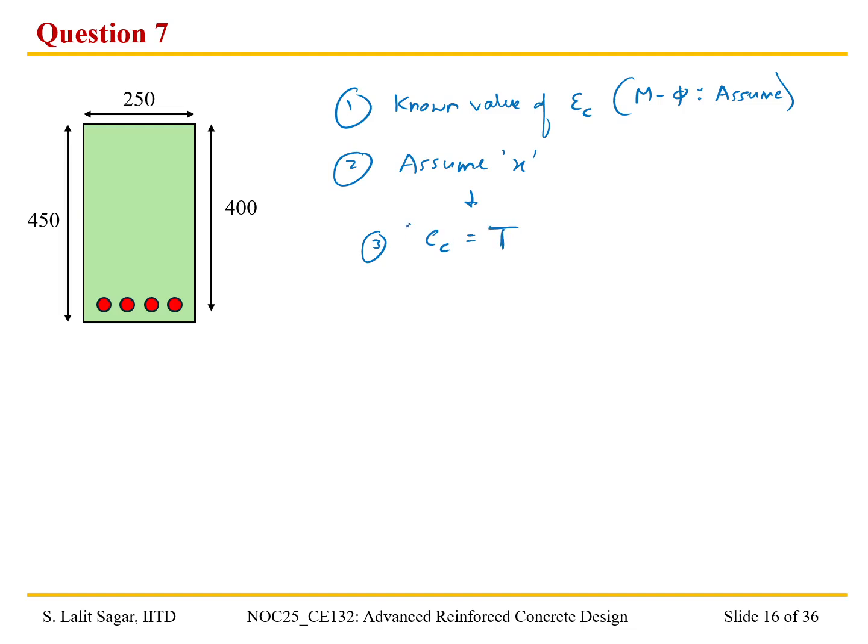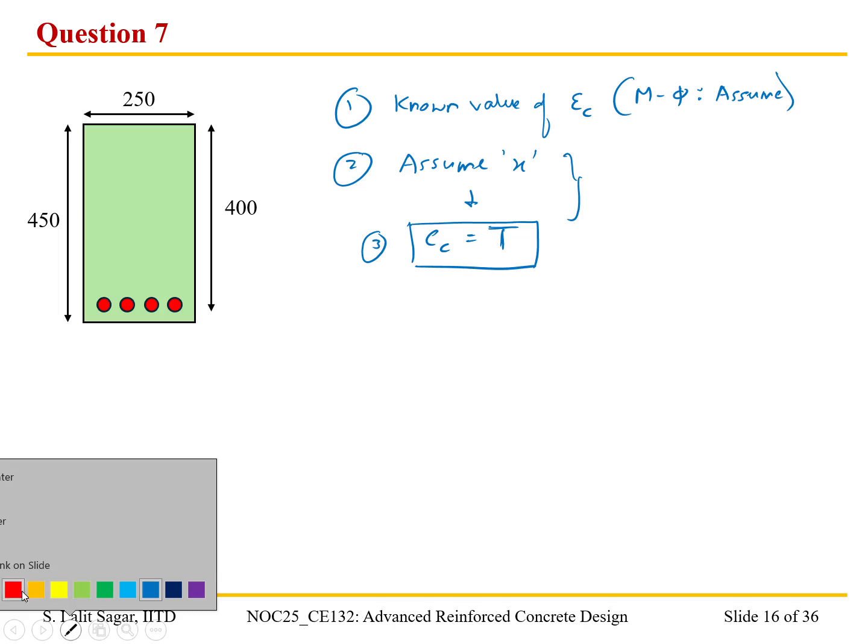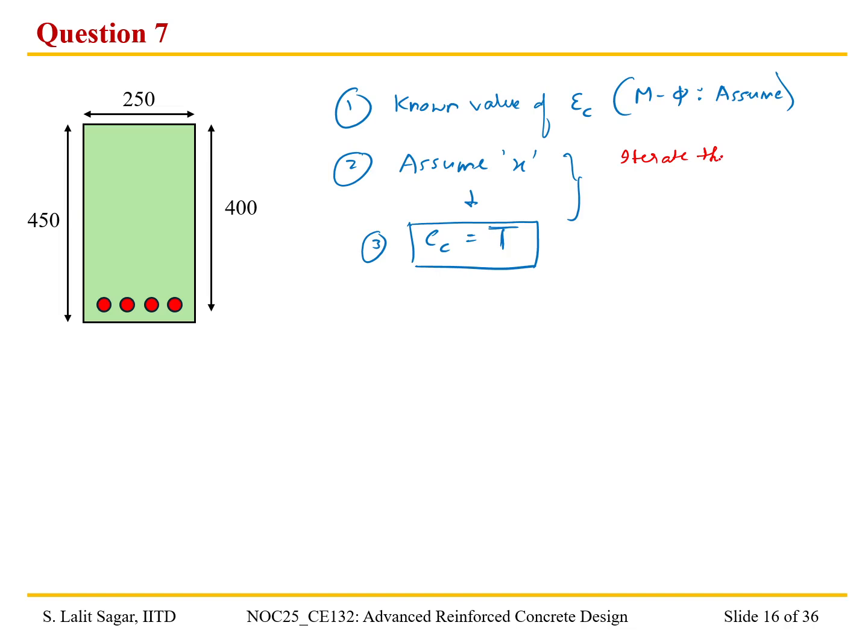Both of them need to match, so you need to iterate the value of x until Cc is equal to T. I'm going to write a side note over here: iterate the value of x until Cc is equal to T.